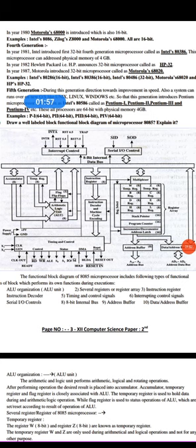Then next we are going towards the temporary register. Here you see two types of temporary register, one very near to the accumulator and the other on the right hand side list of registers. This temporary register holds data temporarily during execution of certain instructions, like internal carries or internal borrow, etc. Then you find the list of registers on the right hand side named WZ, BC, DE, HL. These are general purpose registers.